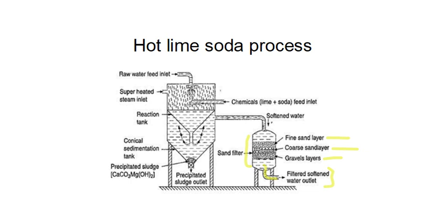Whatever particles could not grow in size and form part of the sludge will come along with water into the side tank, carried up with the turbulence of water. Those particles are trapped in the bed provided here. So the role of this bed is to filter whatever could not be settled down due to gravity in the first chamber.